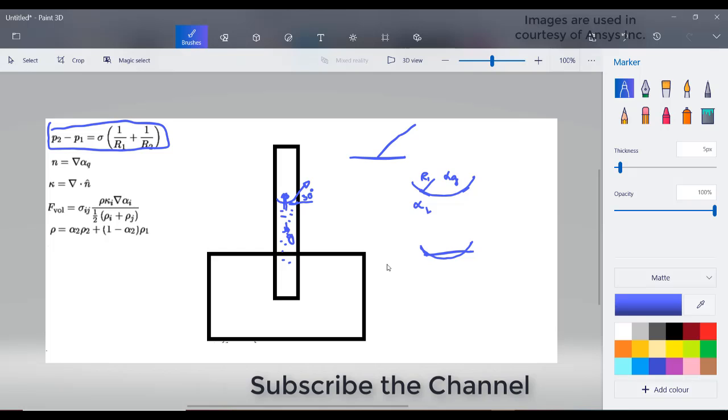We all know the Navier-Stokes equation that we generally use. To that we add this source term, the source term due to the surface tension. In some cases the surface tension tends to 0 when the wall adhesion effect is negligible. The wall adhesion is very high near the wall, but away from the wall there is no curvature effect. If there is no curvature effect, it will not pull in the up direction, so it remains flat.